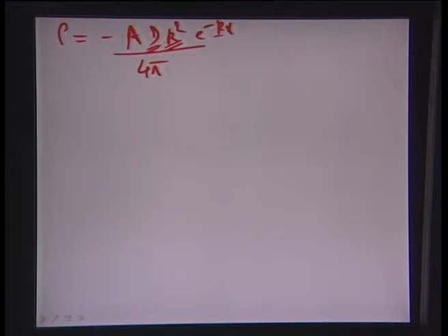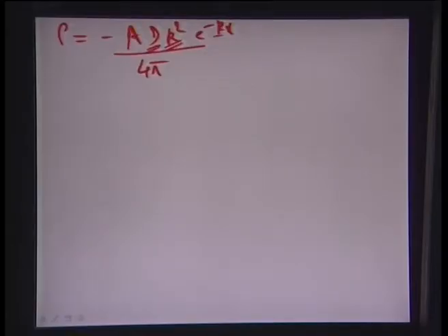If you really look at the surface charge density, and we also tried to discuss this, in the electrode a very critical parameter of importance is the charge density on the surface of the electrode. When we are talking about microfluidic channels, the charge density essentially means the density of the dangling bonds on the surface. If you have a silicon surface and you silanize it and get it converted into SiOH, and then under a certain pH this converts into SiO minus, the charge density on the surface in such a situation would essentially be a function of the bond density on the surface too, okay.